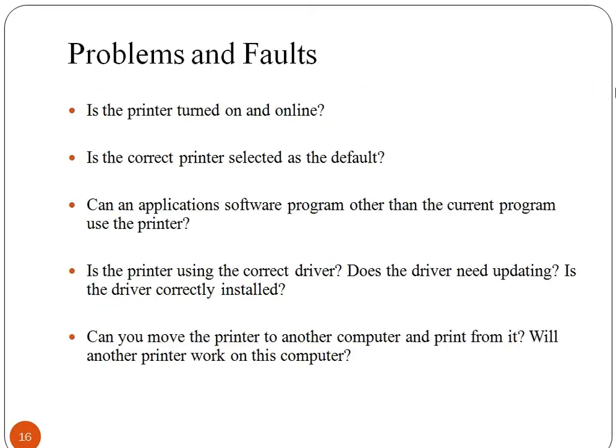Another problem is vertical white areas. To fix this problem, clean the corona wire. This problem is caused by either the main corona or the transfer corona being covered with toner in certain spots. To clean the corona wire, use a special felt-lined tool that comes with your printer.